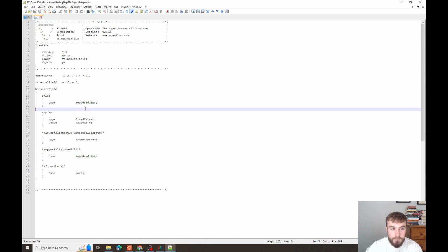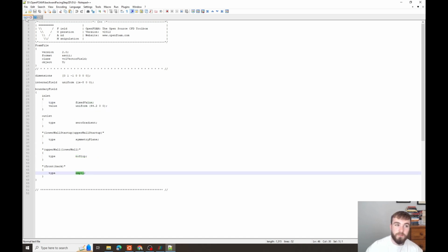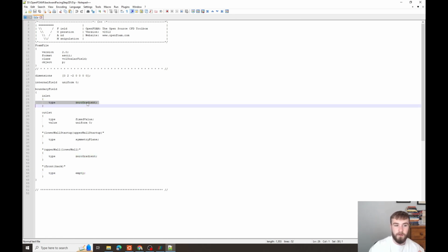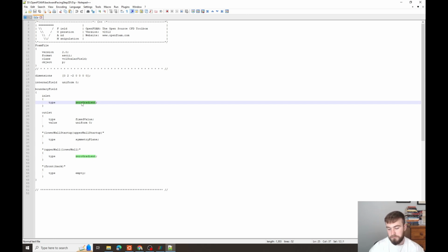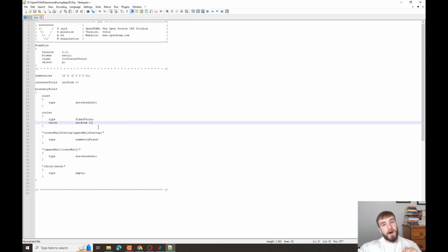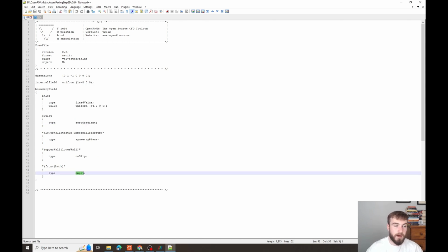So at the inlet, whereas with the velocity case we're assigning a value, for the pressure condition we're saying that the gradient is 0. If I were to change this pressure to, I don't know, 1 atmosphere at the inlet, I would get an error. Same with the outlet, we're assigning a fixed value pressure condition at the outlet, whereas the velocity was 0 gradient. So that's how we're defining our conditions there.